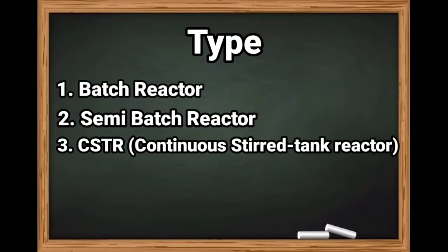The third one is the CSTR, or continuous stirred tank reactor. In a CSTR, one or more fluid reagents are introduced into a tank reactor, which is typically stirred with an impeller to ensure proper mixing of the reagents while the reactor effluent is removed. Dividing the volume of the tank by the average volumetric flow rate through the tank gives the space time, or the time required to process one reactor volume of fluid. Using chemical kinetics, the expected percent completion of the reaction can be calculated.